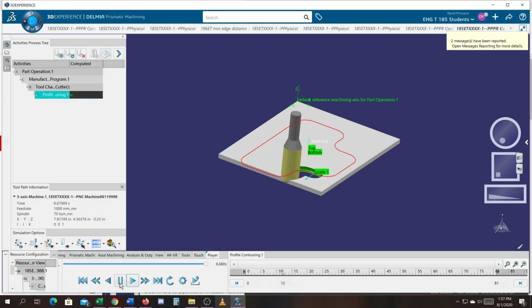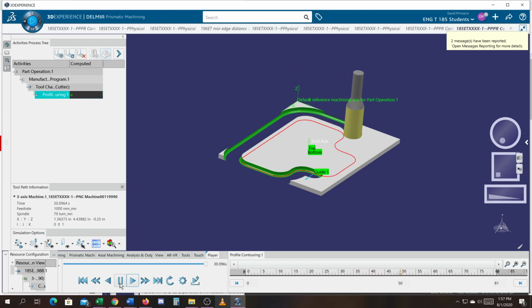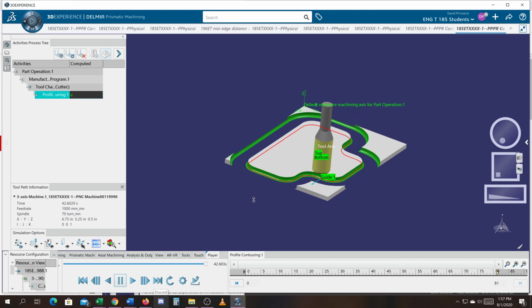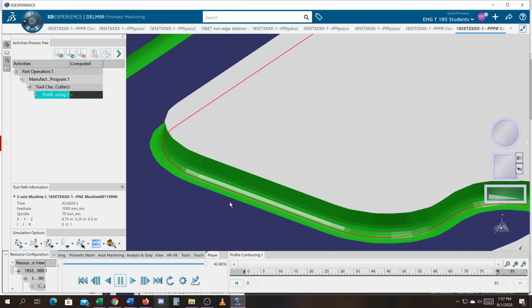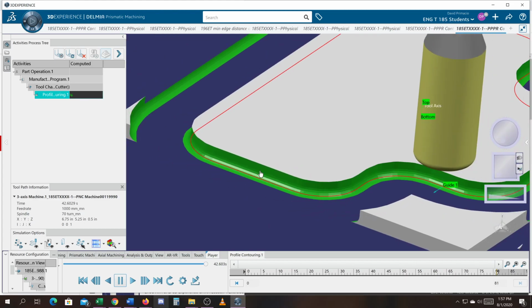And, oh, I did cut through. How did that work? Oh, no, see, I didn't cut enough through it. So what you're seeing is I don't need an end radius here. I knew what I was doing. That fillet right there is a 1/16 of an inch, so I would go an 1/8 of an inch past the part. When it sits on the tool, usually there's a groove big enough for the cutter to follow where it's not hitting the tool because it's already been cut out. So I'm going to exit out.